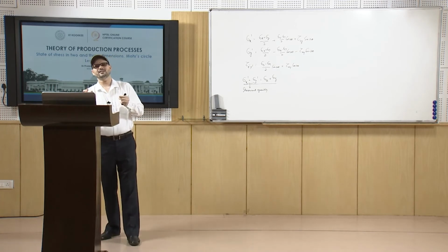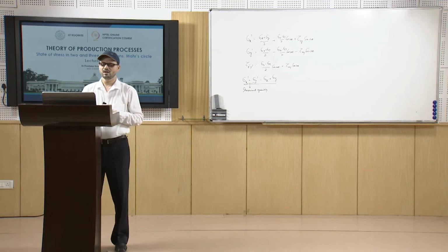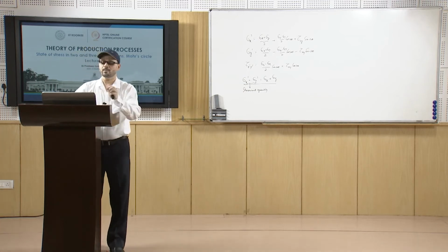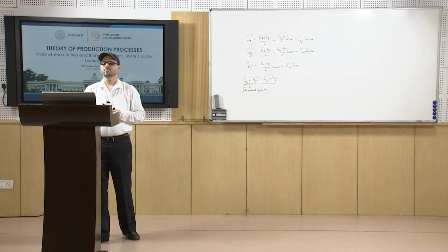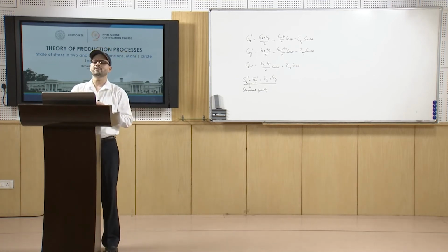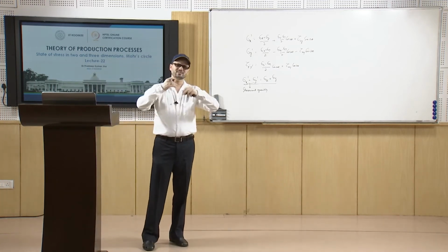From 90° apart, these maximum and minimum values of normal and shear stresses occur. The maximum value of the shear stress occurs at an angle halfway between the maximum and minimum normal stress. This is the third finding.